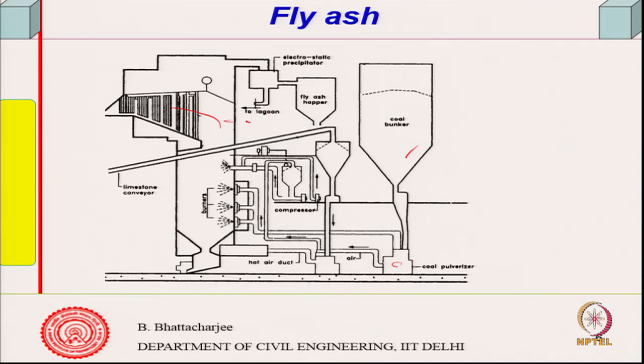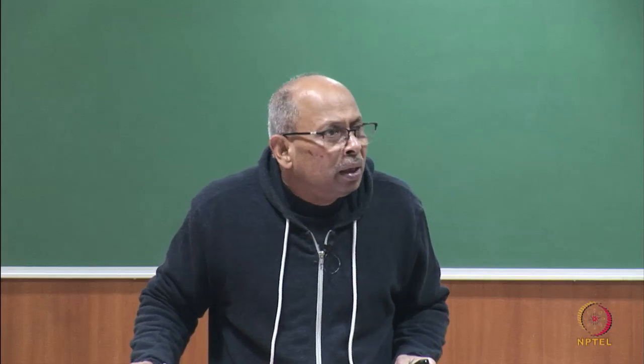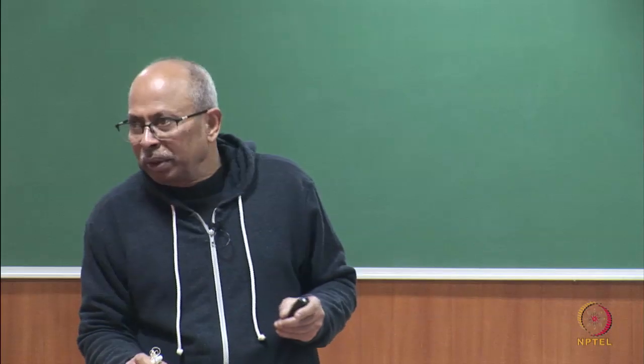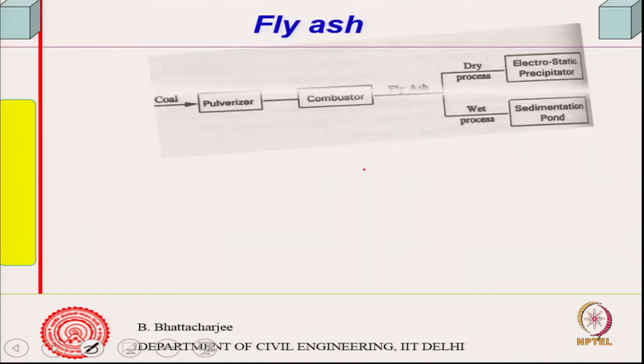This goes either to a lagoon where they are stored, because fly ash is a waste. So, you will find somewhere there are what they call ash ponds, right, ash pond, and others could be in a hopper. So, bottom ash goes to the ash pond generally together with some fly ash, but nowadays it is not recommended that fly ash should be sent to the ash pond, because if you mix it up with bottom ash, then they are not useful actually. So, if you mix two things up, it is not useful, right. So, this is how it is produced actually.